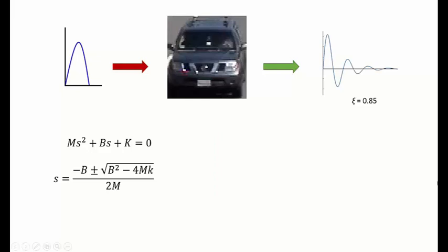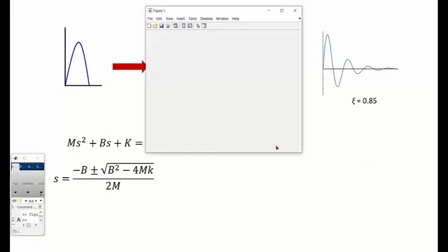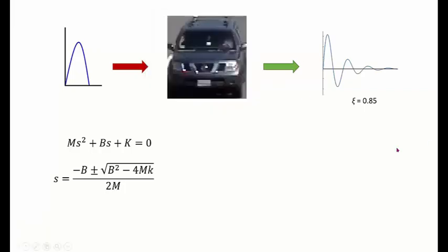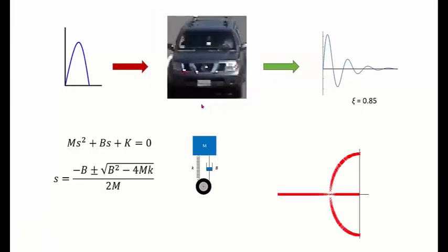You drew the root locus of the roots on the S-plane by varying b from 0 to infinity, and what you got was a graph shown over here. So when you varied b from 0 to infinity, this is how the behavior of the plot was obtained. Now, since you assume that the mass that will be put on the suspension system is known, the spring constant is known and fixed, the only thing that you can change is the value of b. Thus, by varying this value of b, you observe that the roots move in this fashion. So in this particular system, we consider b as a design parameter which is allowed to be varied or changed in order to attain the desired response of the system.